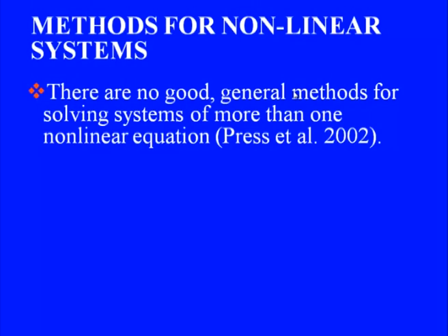of roots which we can definitely obtain for that particular equation. But the moment we are dealing with more than one equation, and that is what we will have in CFD analysis, we will have not just one, we will have a system where the number of unknowns would be in millions or billions. So we will have a system of millions or billions of nonlinear equations which ought to be solved. And this observation says that there is no general method available which can guarantee a converged solution for us. But nevertheless we have got to live with it.